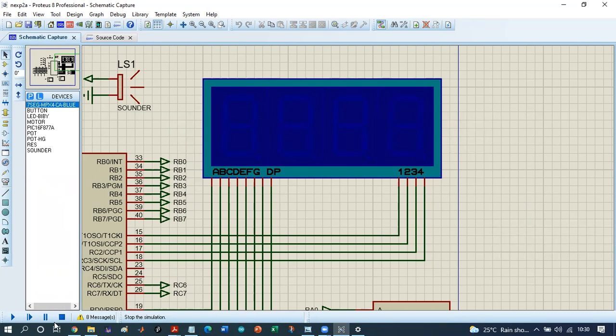Because this lecture is just a basic introduction, when you really want to check the time, you go into things like the debugger, step into and step through to measure the time. You put breakpoints in between the code, then use an oscilloscope to measure it.